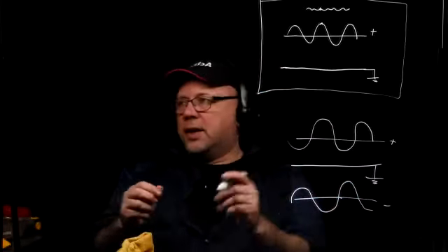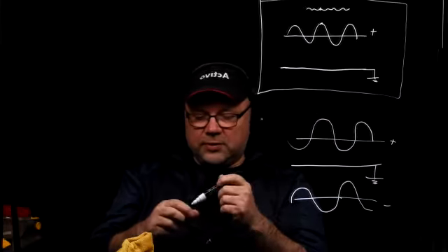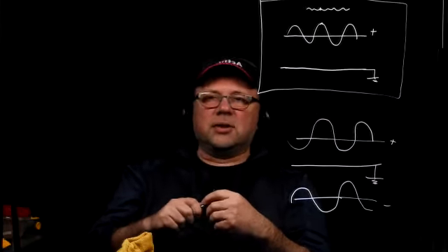Okay, so this would be something like this, and here, and here. See that? So those signals are 180 degrees out of phase, and at the other end of the line, what receives the signal is something that's called a differential amplifier.